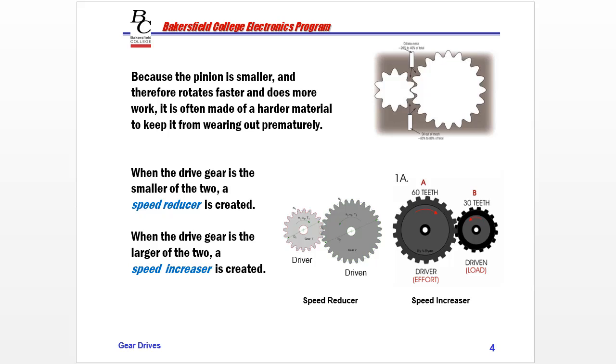We don't need that high torque once that vehicle is moving, or we can put this into industry, once that machine is moving and up to speed. We don't need the torque that is going to be supplied by a speed reducer and a torque increaser. So as we shift those gears in a manual transmission in an automobile, our torque goes down every gear we go up. And you'll actually see that relationship. So watch that video in this week's video section.